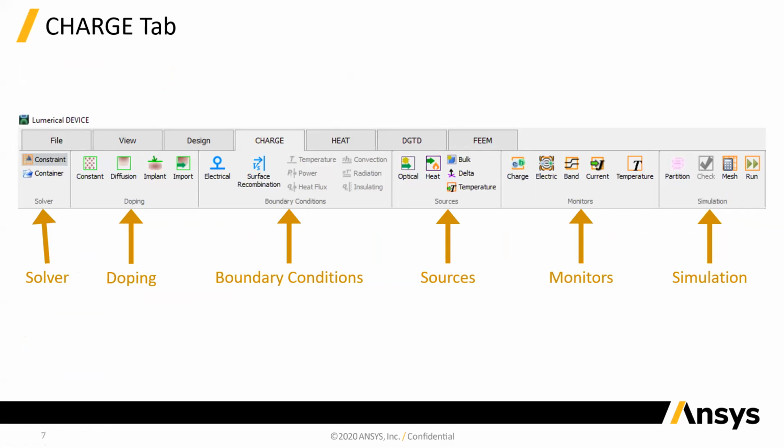However, there could be certain regions where you want the mesh to be finer because maybe the charge is varying really fast there, or there's some phenomena going on that you want to capture very accurately. You can put a mesh constraint in that volume or area and then make the mesh finer than it normally would be. So that's where you would use this particular simulation object.